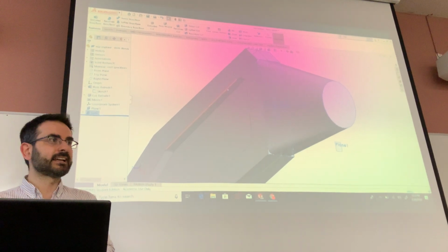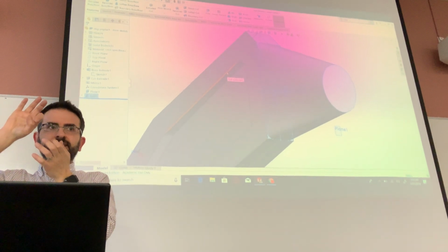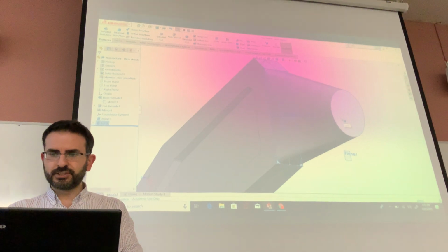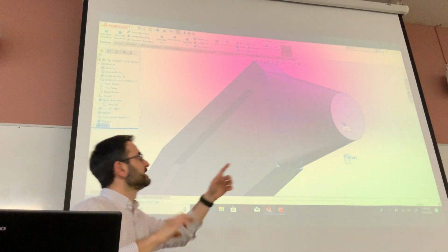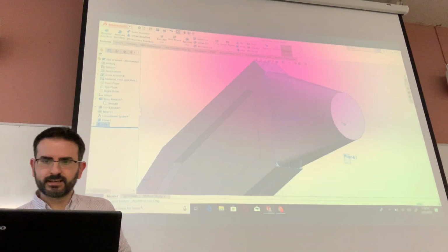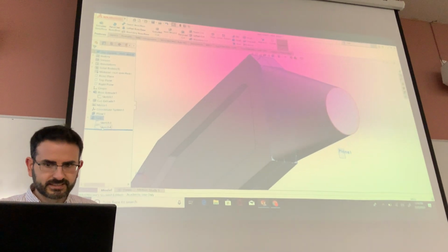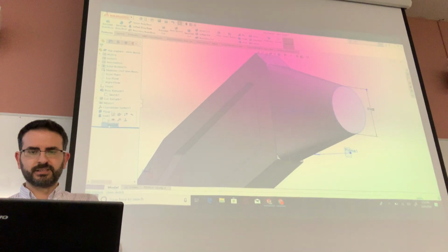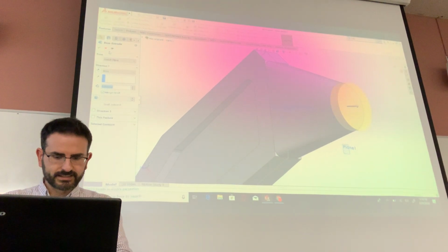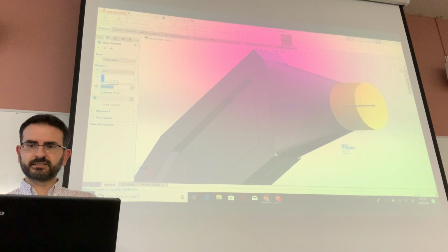Then next step, we need to finish the neck, and then we can work on the femoral head. So the neck, to finish it, we need a little bit more like a cylindrical shape that protrudes from this. And so I'm gonna select that geometry, which is sketch number 4 for me. It's that one, and I say extrude. So this is like a simple extrude by 10 millimeters. Okay, I like it.